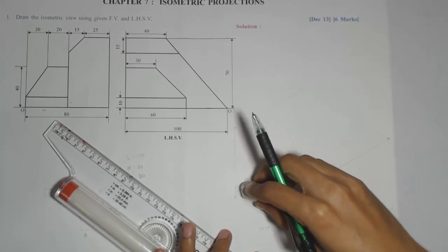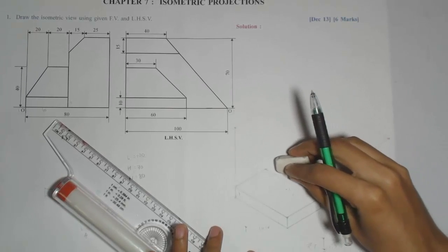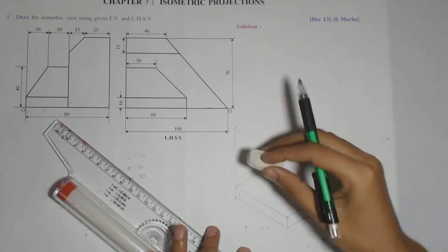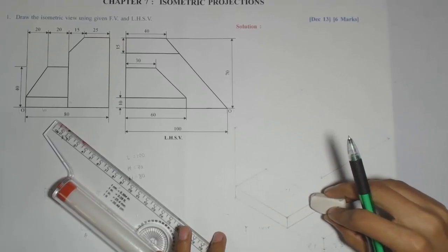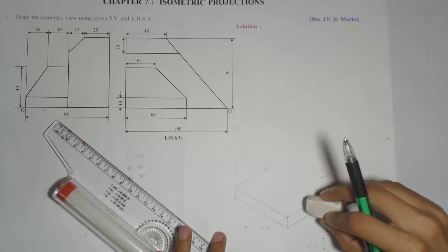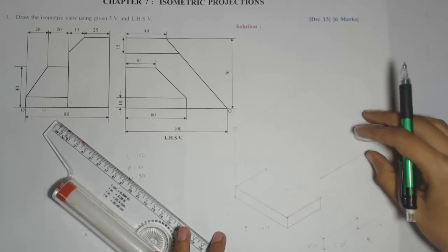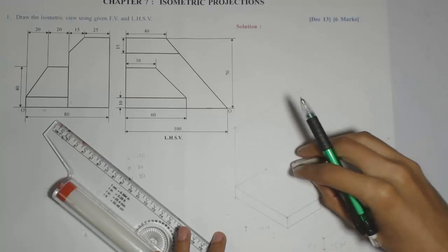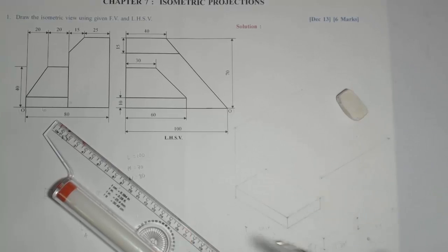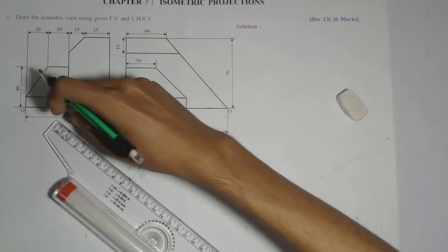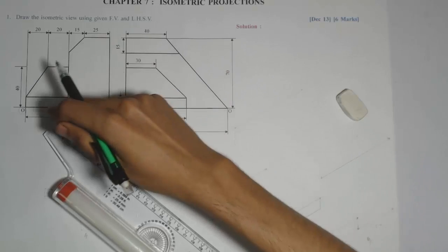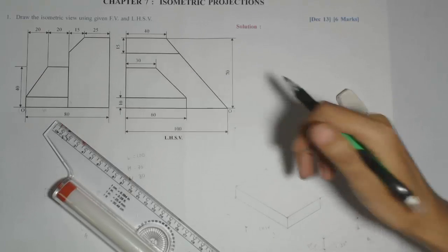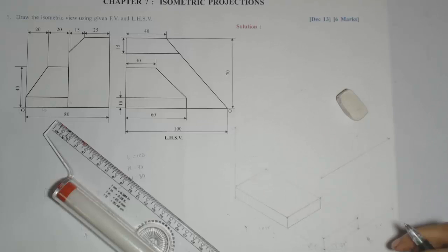I have drawn all those lines because I need a generalized procedure. So we are drawing those projectors from each corner, not leaving any corner. But by practice, you will learn which projectors from corners you should draw, and which you can omit. So for these two corresponding rectangles 1040 and 1060, we have got this particular shape.